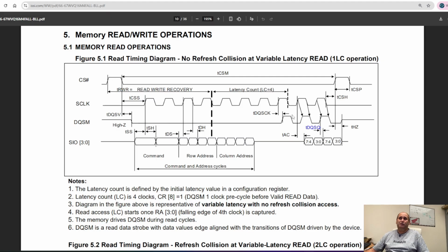So when you see this, the first clock here, this actually signals that data is about to show up after this. So internally the controller is sampling this signal, and when it sees this strobe, it says, okay, data follows. And so basically the controller just sits here in this state until it gets this signal, and then starts reading the data.